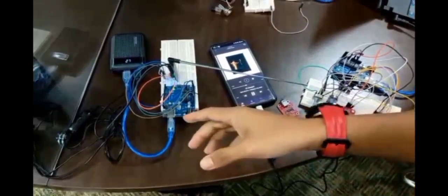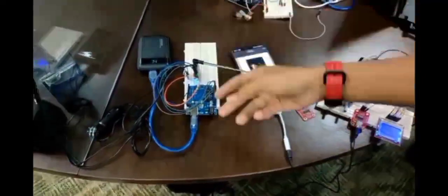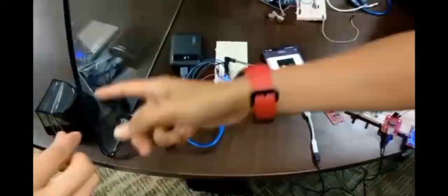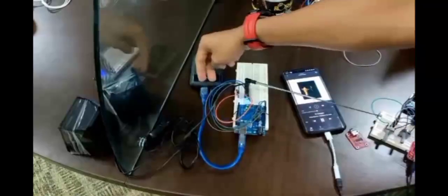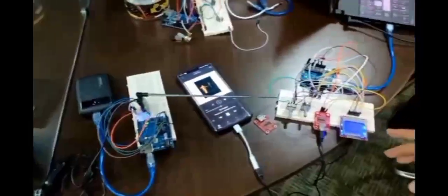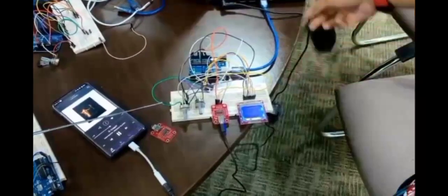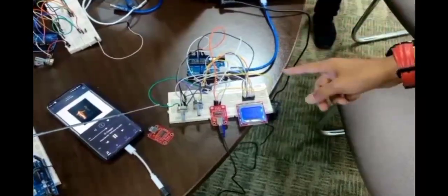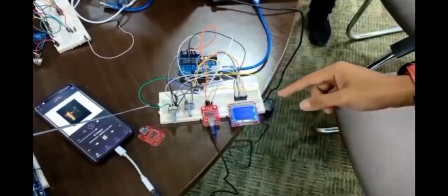This is our receiver part. We connect the source from a power bank and the speaker also to the power bank. So this is the input to the source. For the transmitter part, the power supply is connected from the laptop, and we set the transmitter to 100 megahertz.